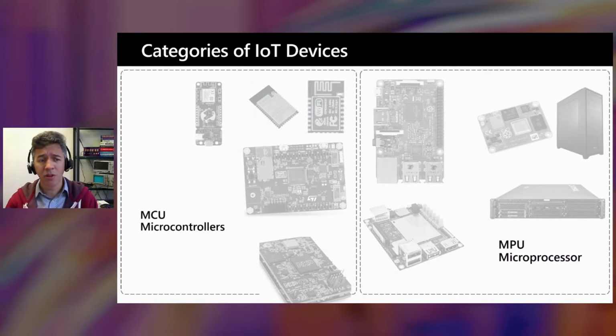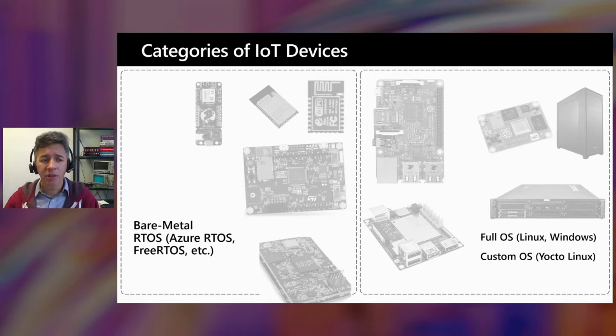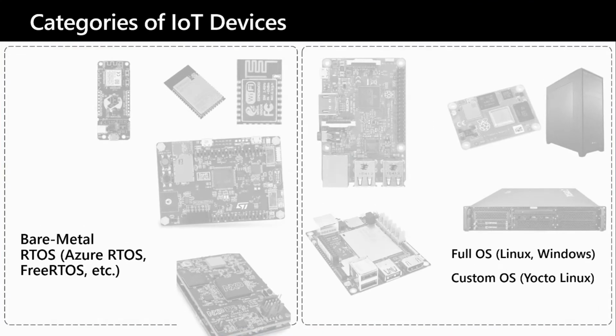That's not the only one. We could also look at this distinction between microcontrollers, or all of these devices that are based on microcontrollers, going all the way to microprocessors. Another way to look at these could be maybe a category that can run bare metal, like all of these microcontroller-based ones, or a real-time operating system like Azure RTOS, FreeRTOS, and so many others, moving all the way to devices that will be running a full operating system, like Linux or Windows, or even custom OSs based on, say, Yocto Linux.